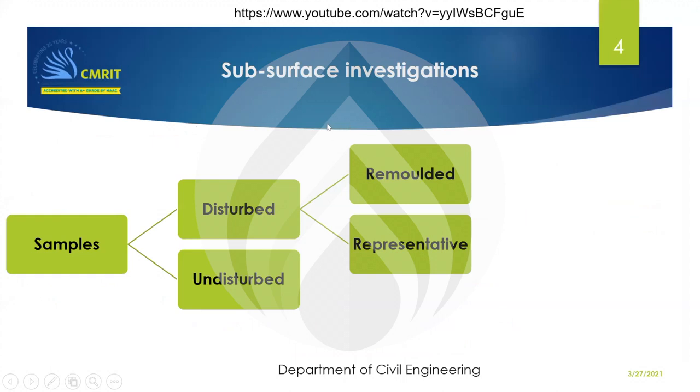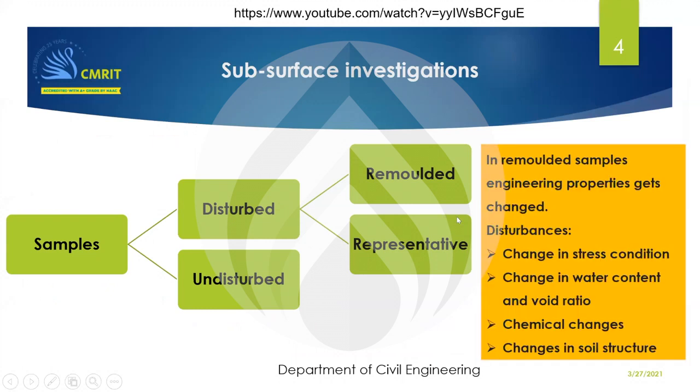Generally, whenever we do any type of investigations, we have disturbed or undisturbed samples and remolded. The disturbed samples can be either remolded samples or representative samples. For remolded samples, it will be very difficult to ensure the soil is stratified.